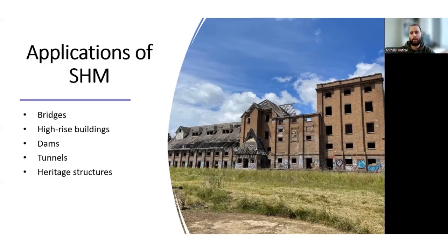If structural health monitoring has not been considered at the design stage, however, installation of permanent sensors can be very expensive, as often they would need protection from environmental factors and other installation considerations, such as if it is in, for example, a foyer, you need to protect from people. This is where non-destructive inspection methods help by providing periodic data collection to help assist with any sort of early detection of deterioration.